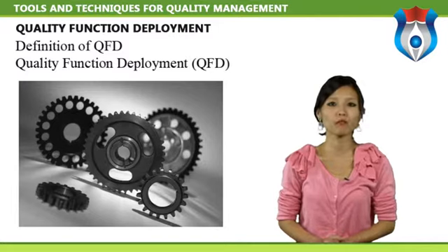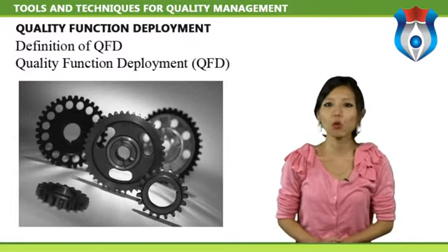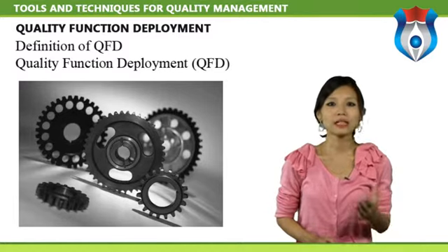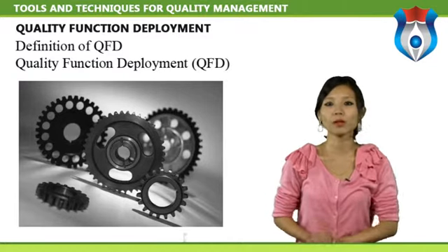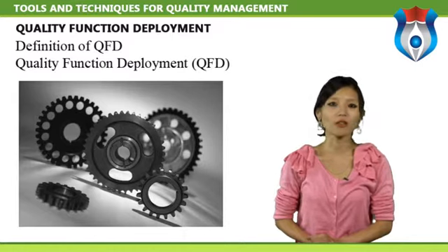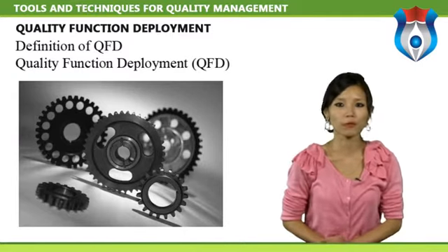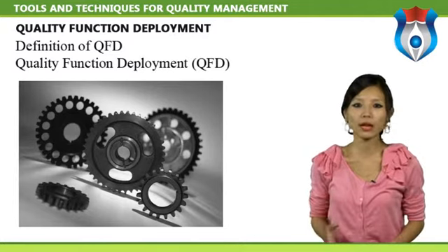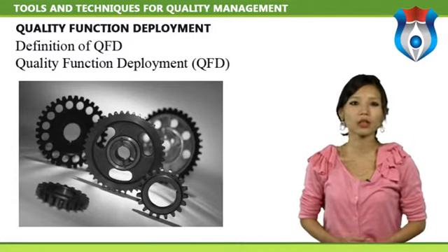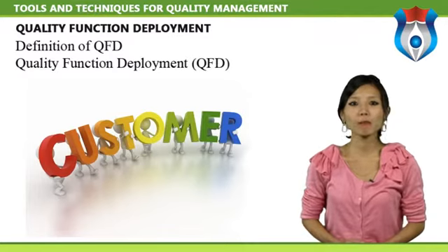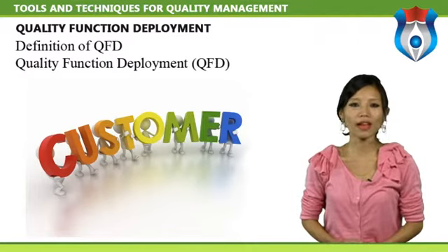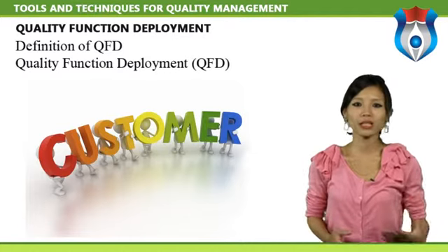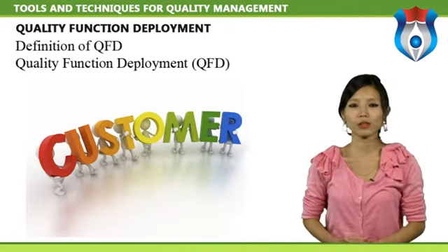Definition of QFD. The QFD stands for Quality Function Deployment. Quality Function Deployment, QFD, is a systematic way for developing products based on the needs of the customer. It is a structured product development process which translates what the market requires into a program to create, manufacture and deliver it. In a QFD process, multi-skilled teams collaborate to arrive at a common understanding of the customer needs and determine the appropriate technical requirements of each stage.